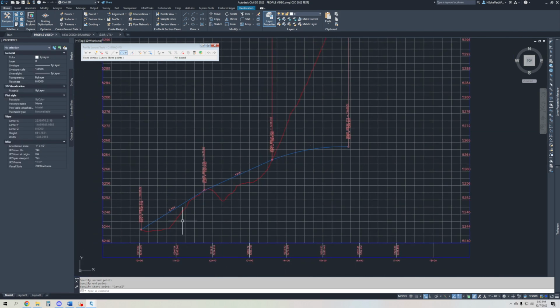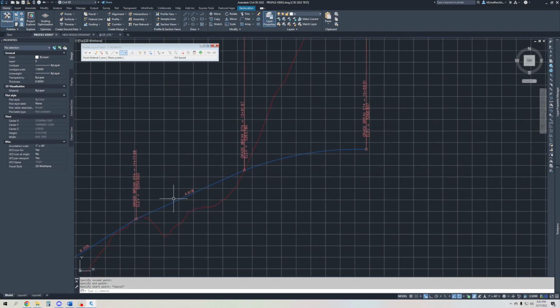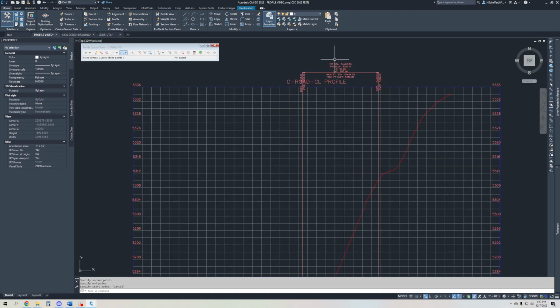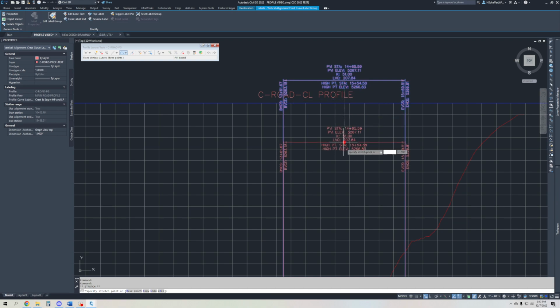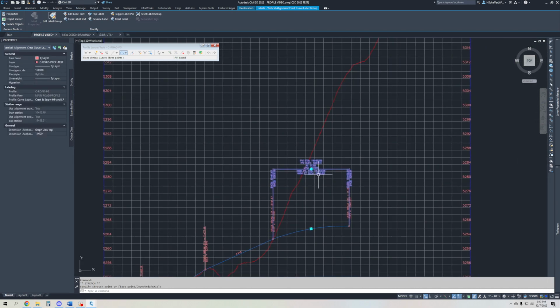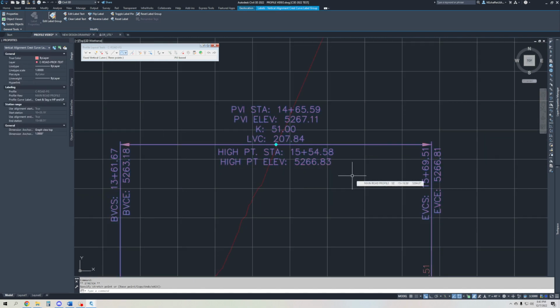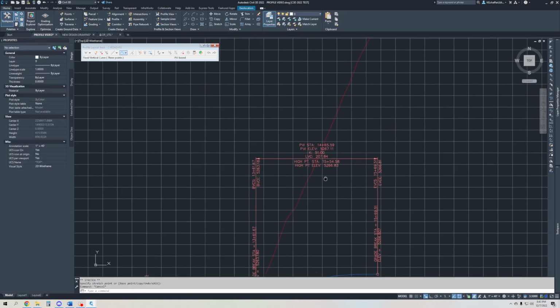So now in this case, it's going along. You have a rough change of a little under 2% grade change, and then now it curves. So now this is a smooth transition. It makes for a very nice curve over your road. So this is what would be considered a vertical curve. You'll hear that a lot with roads, and typically roads and parking lots will have vertical curves going between two different grade percentages, as we have here.